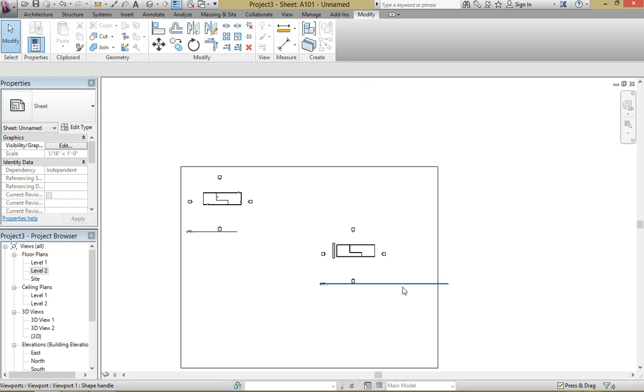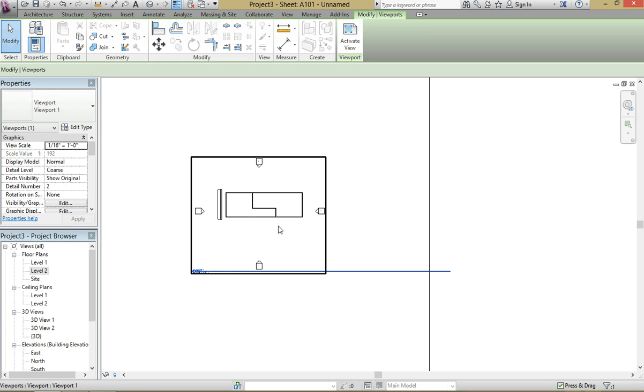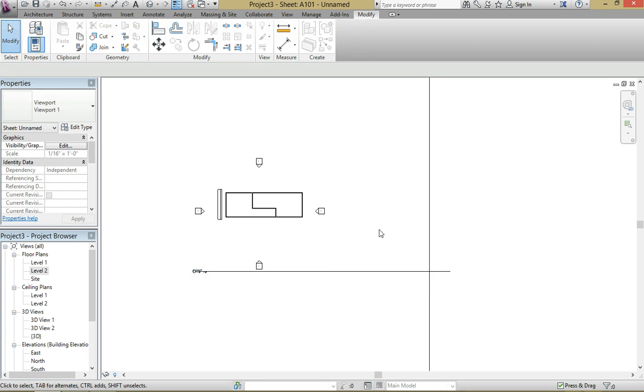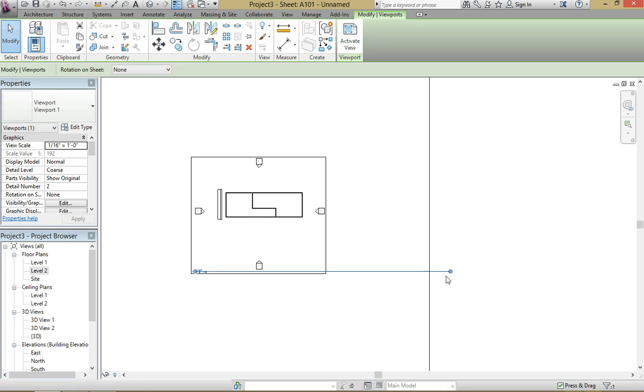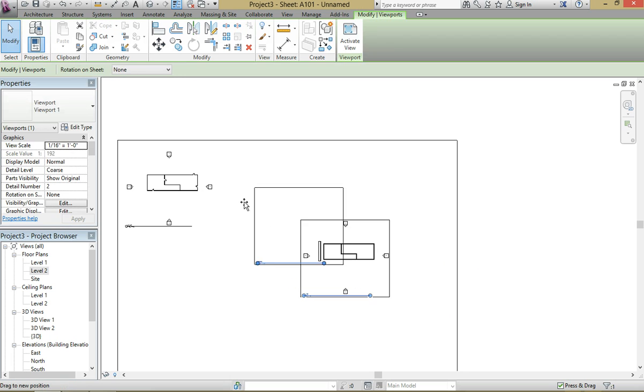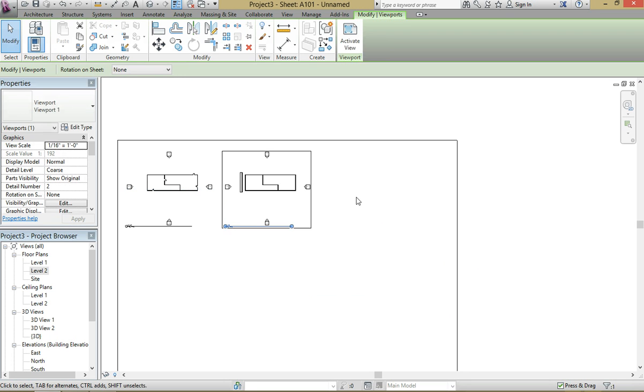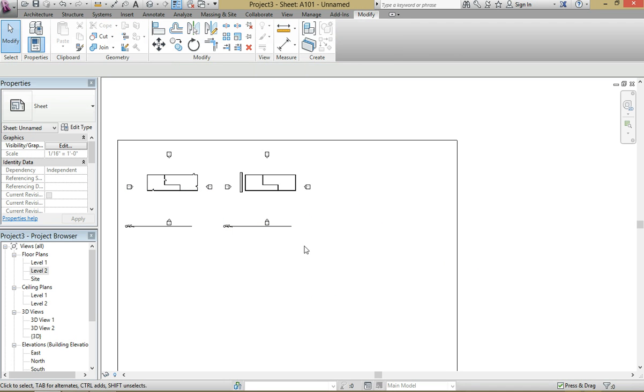Now this thing here is really tricky. It took me a bit to figure this out, but you know how I changed the measurement on the other one? This one it's not letting me. That's because you have to click the view before you can change the measurement. So just keep that in mind. It's one of those quirky things that if you don't know why it's doing it, it frustrates you to no end.